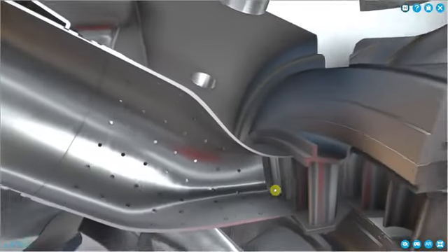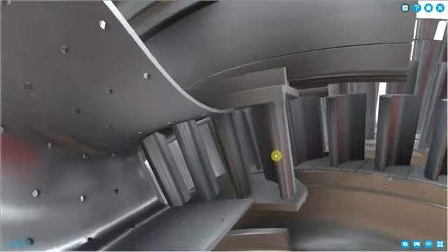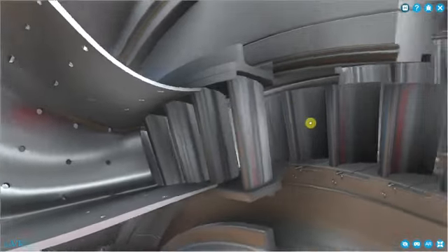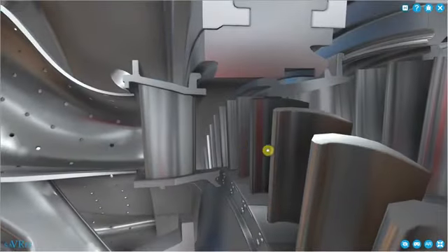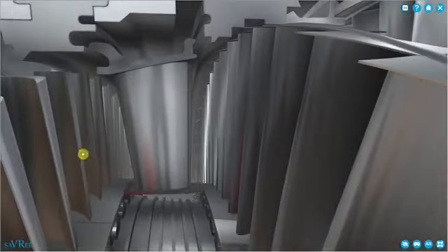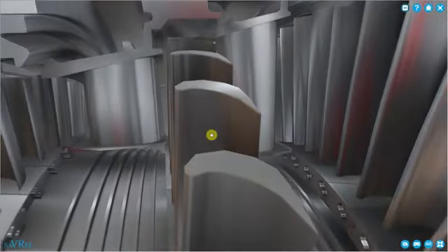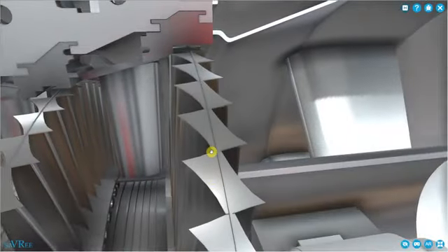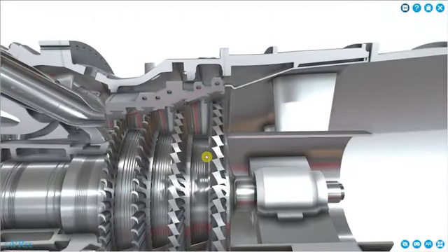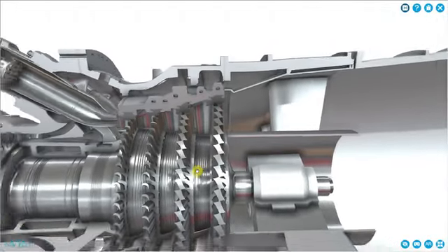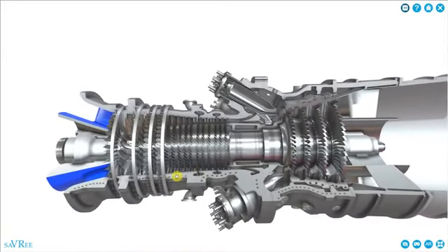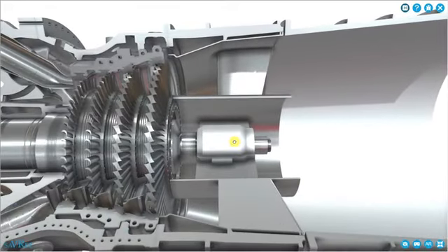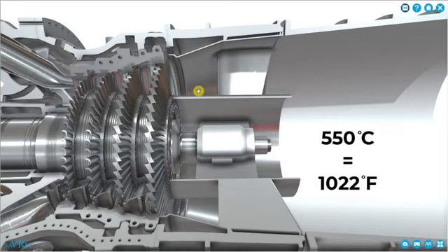The hot air that's being heated is then going to be discharged through nozzles, through these here. The nozzles are stationary, and we pass the hot air across the blades of our turbine. You can see here is one set, here's the next set, and here is the next set. Those turbine blades will rotate, the central shaft will rotate, and we can connect the central shaft to the generator to generate electricity.